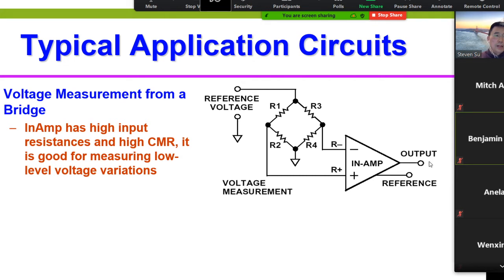How to measure it: if you have an output, this is called the common mode output. The common mode output divided by the common mode input. For example, if your input is 10,000 volts and the output is 5, it's 5 divided by 10,000. It's very small, but it still has a value.